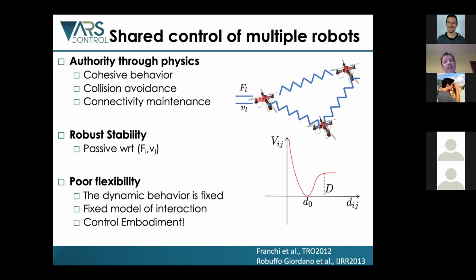But passivity is more. Passivity does not require that the controller has to mimic a physical behavior. Passivity requires that the overall system has a certain energetic behavior. So we should not embody passivity, but we should consider passivity for what it is, namely energy flows.